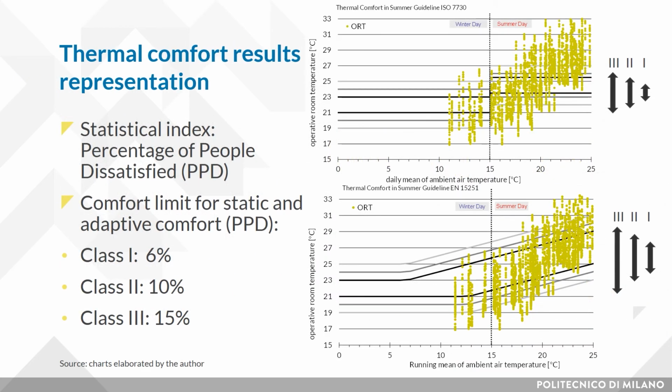A specific task in building simulation is related to the thermal comfort level analysis. In this respect, the line chart representing the temperature fluctuation in a zone does not clearly show the intensity of the perceived potential discomfort. The European Comfort Standards EN 17037 and EN 15251 present a method for predicting the overall thermal sensation and the degree of discomfort.